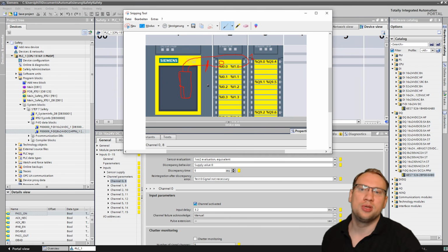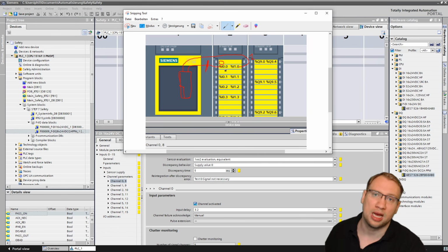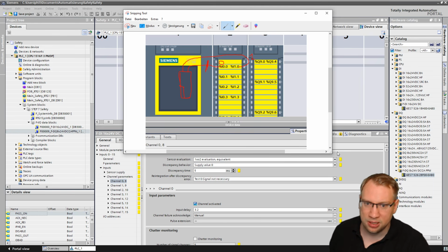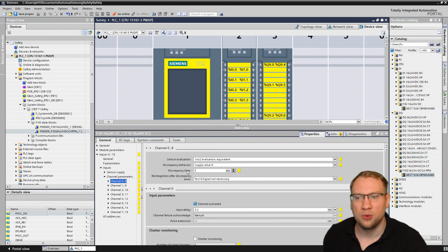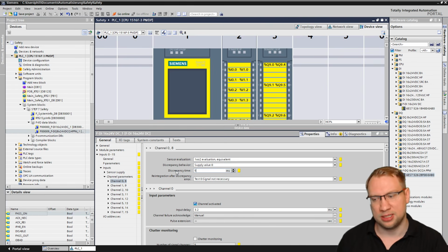Yeah, so you can set that. Right now, we would have this discrepancy, so the channel would analyze it and your safety program would directly react on it. What does directly react on it mean? First of all, we have to set a so-called discrepancy time.